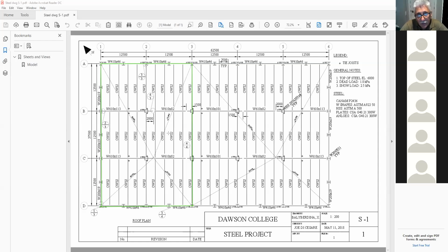That makes sense. That would be the ideal location for a roof drain, you understand? If you're doing reinforced concrete, it really doesn't matter, because you just tell them to slope the concrete there, and you put it right where the deflection is going to be the greatest. So in reinforced concrete, I would put it right in the middle of my panel and tell them to slope the concrete there. Okay?